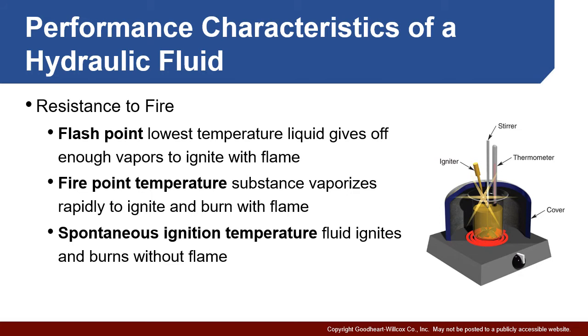And this is essentially when the oil will just ignite on its own. If you get fluid hot enough, it'll just burst into flames. So we want to make sure we avoid that. Generally, if you keep it below the flash point, then you won't have to worry about these other two, but you should realize that there are some differences. And keep in mind, just solving the problem of not exposing a system to open flame solves most of the problems, but you still have to be careful about how hot oil or other materials for that matter get before they could spontaneously ignite.